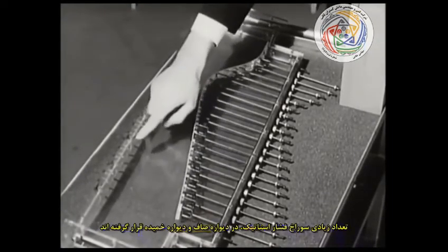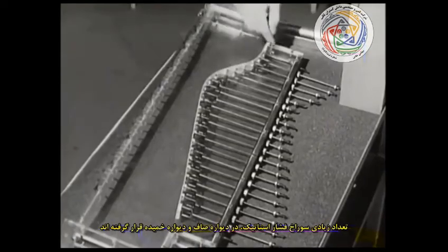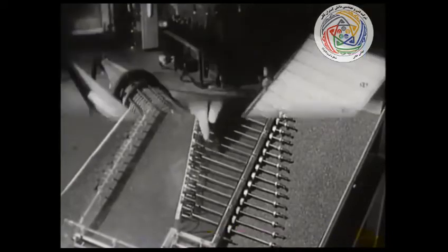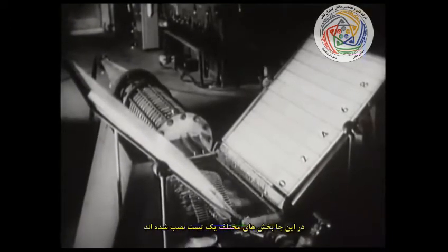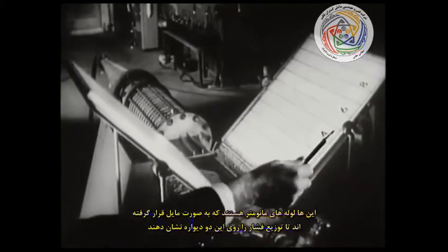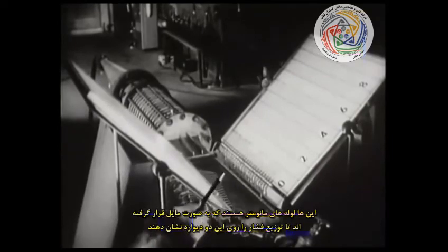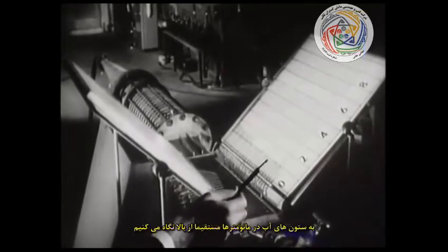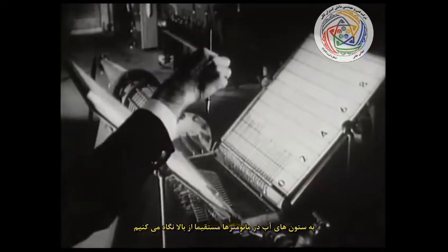A great many static pressure taps are in the straight wall and in the curved wall. Here it is set up for test. These are inclined manometer bores to show the pressure distributions on the two walls. We will observe the lengths of the water columns looking down from a position directly above.